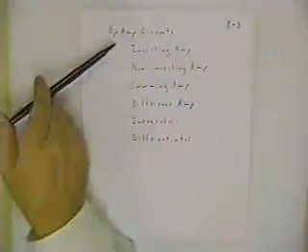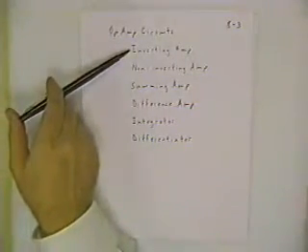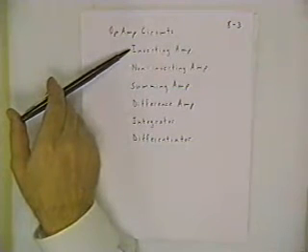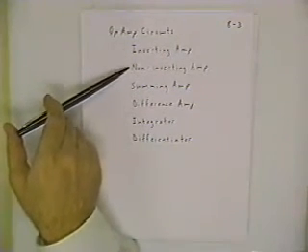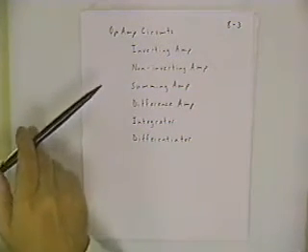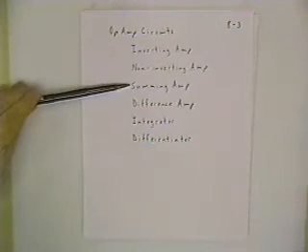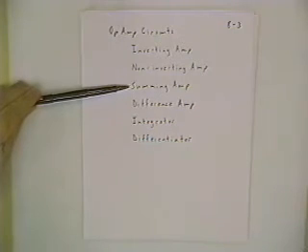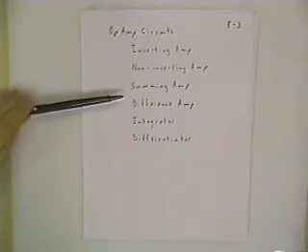So I think what you'll appreciate from this next slide is where the op-amp gets its name, and also why it's a useful thing to know about for all engineers. The op-amp can be used as an amplifier that inverts the output with respect to the input. You can make an amplifier that doesn't invert and doesn't cause that 180-degree phase shift. You can take several input signals and add them together with different coefficients. So you can do a weighted sum of inputs. That's called a summing amplifier.